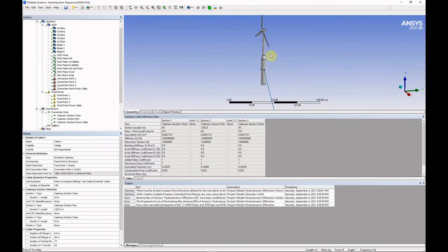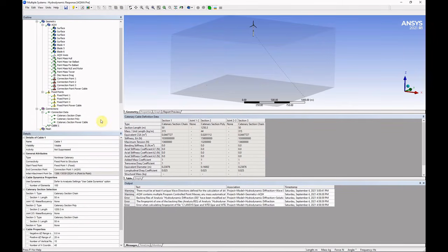This mooring line system is called taut leg, which has all its length under tension and no section resting on the seafloor. In this case, the anchors need to hold vertical loads as well.